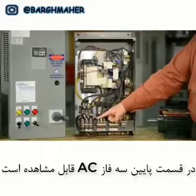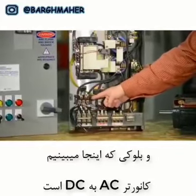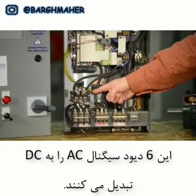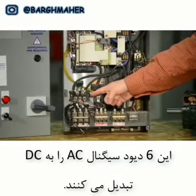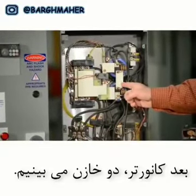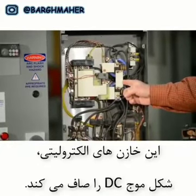We come in down here with three-phase AC, and this block that you see right there is the AC to DC converter, or the diode block. There are 6 diodes in there, and they convert the AC to DC. Then we come up here. These 2 blue cylinders are called capacitors. These are electrolytic capacitors that smooth out that DC.